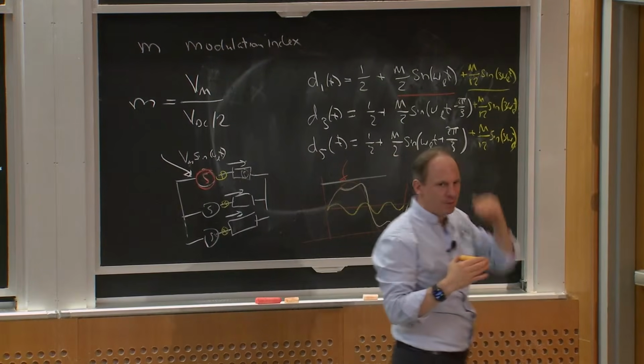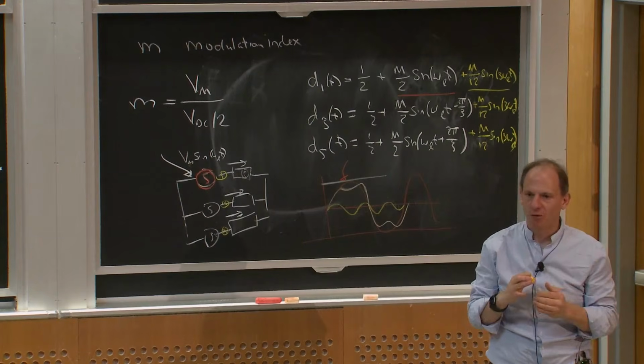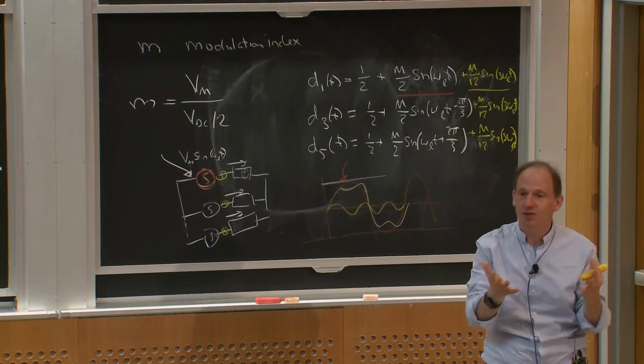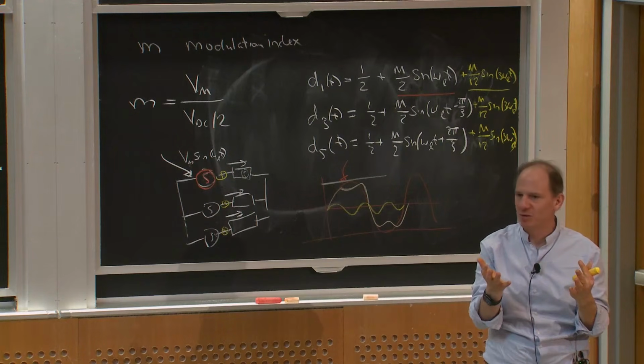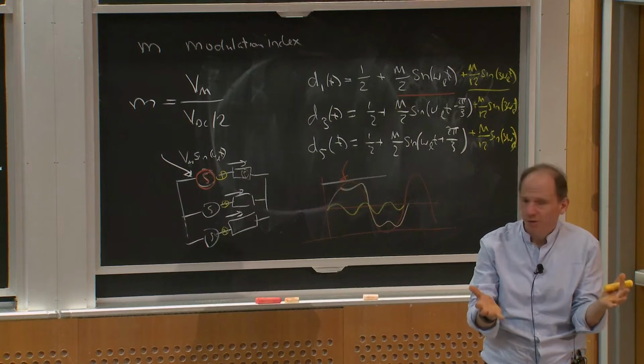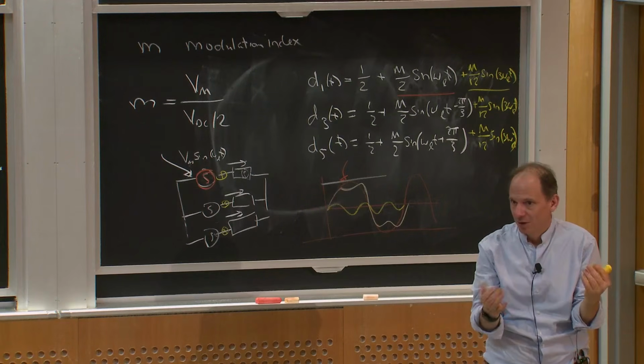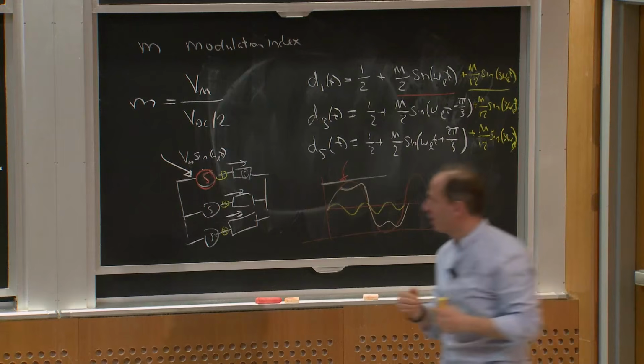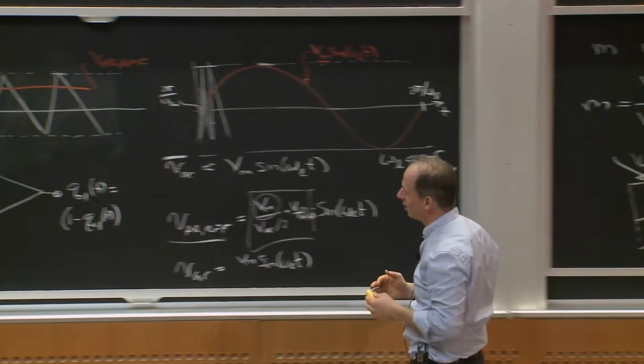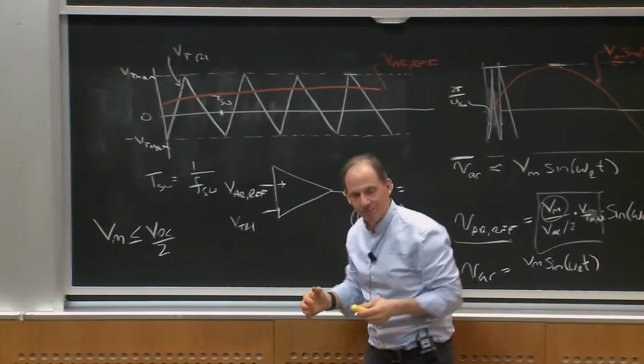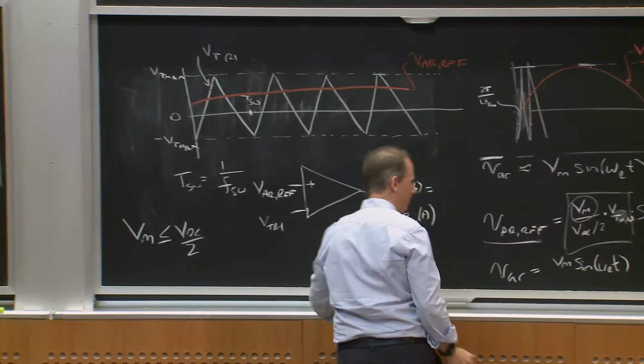That gives me a little bit more headroom to synthesize more voltage, and we're often constrained by how much voltage we can synthesize with our inverter. What do I do if I'm not happy about that? Well, I could just keep turning up M beyond 1. What happens if I turn up M beyond 1?